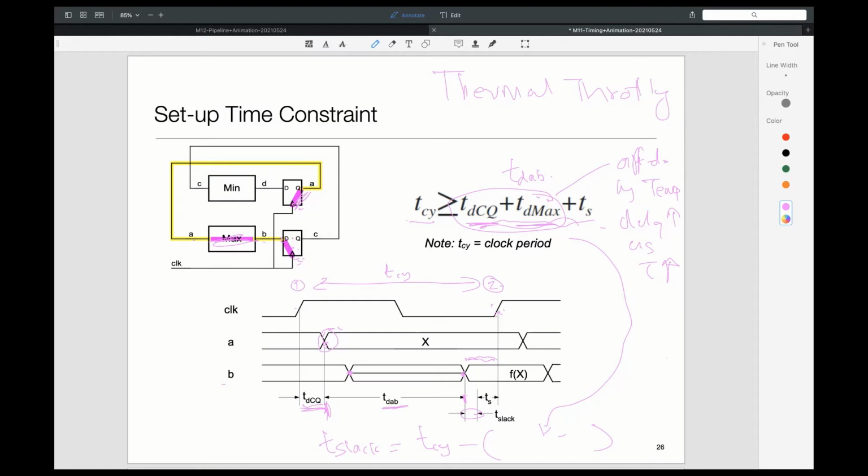And actually, I also didn't mention that as temperature goes up, the gates also consume more and more power, so basically more and more power for the same operation. So if you don't react with thermal throttling very quickly, then the temperature inside the chip will just keep going up and up, and it can hit really, really high temperatures. If you look at some of the papers, the temperature inside can hit nuclear reactor type temperatures if you don't do anything, which is why cooling is done, to keep that temperature under control.